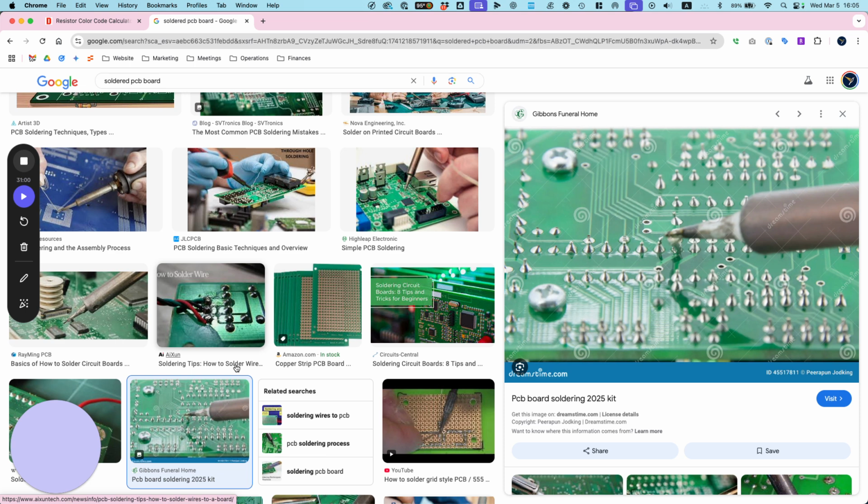What doesn't matter is your capacity, because we're talking voltage. If this was double the size, because it was a 4S 2P, it's still the same voltages, right? Because we're talking parallel. Parallel voltages are the same, okay? So you would still use the same thing. So really what you look at is the number in the series. That determines your range of voltages that you deal with here.